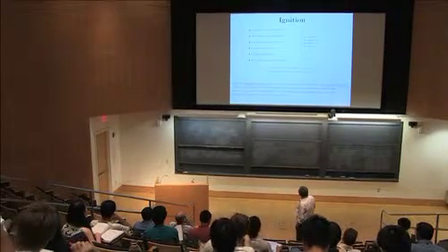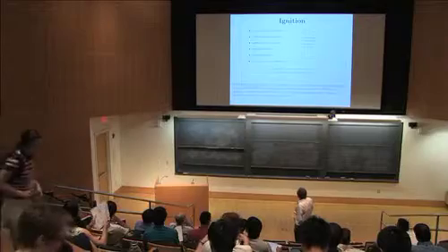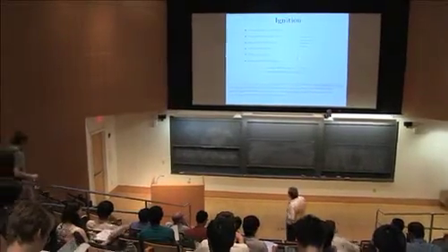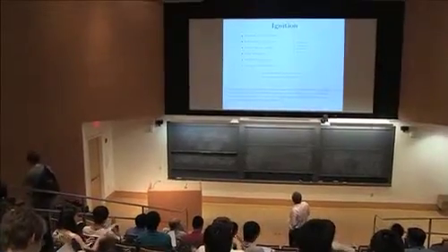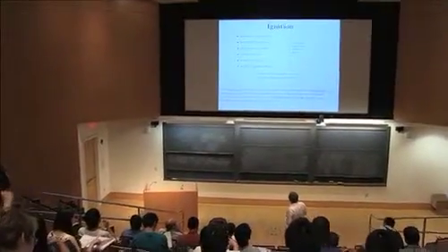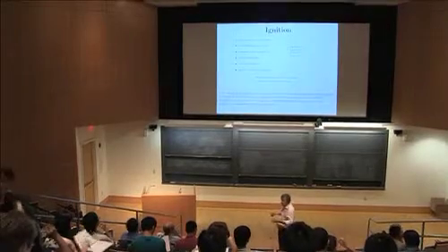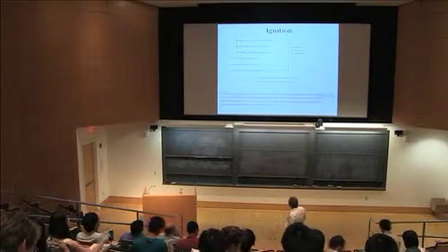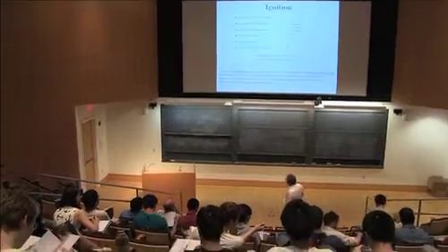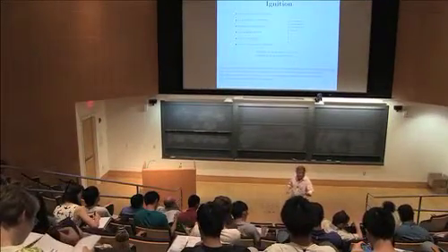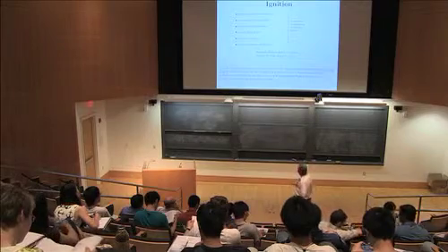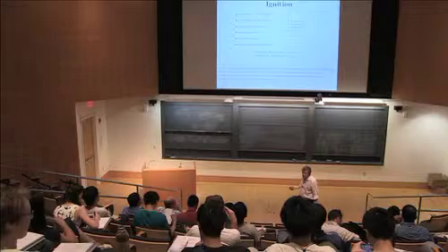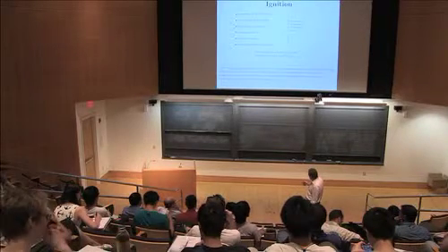An important thing that I want to mention is that the ignition limits are not the same as flammability limits. Flammability limits relate to conditions on composition or pressure beyond which a combustible mixture cannot be made to burn, which means that a self-propagating flame cannot be sustained. But that's irrespective of the ignition source, right? So ignition is something else.